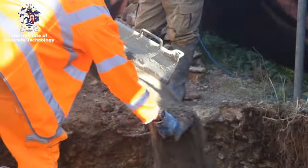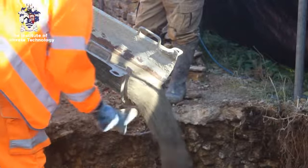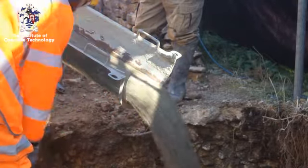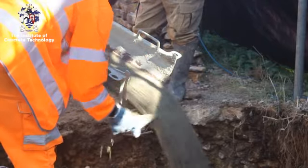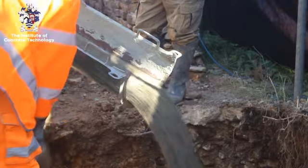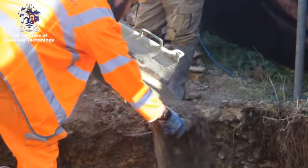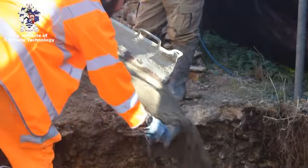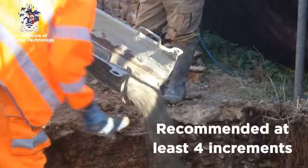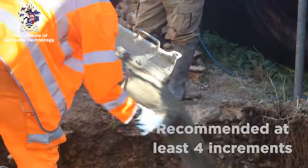The ideal way to take a sample is from a moving stream of concrete, and this can usually be done when the concrete is flowing down the discharge chute of the mixer. The first part and the last part of the load should be disregarded. It is important that the samples are taken from the entire cross-section of the stream, as otherwise the sample may be biased. It is recommended that at least 4 increments are taken for a composite sample.